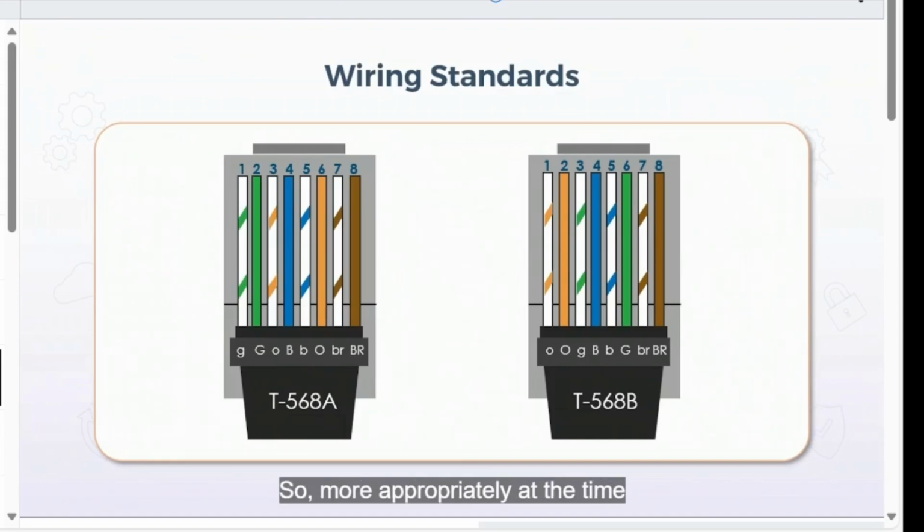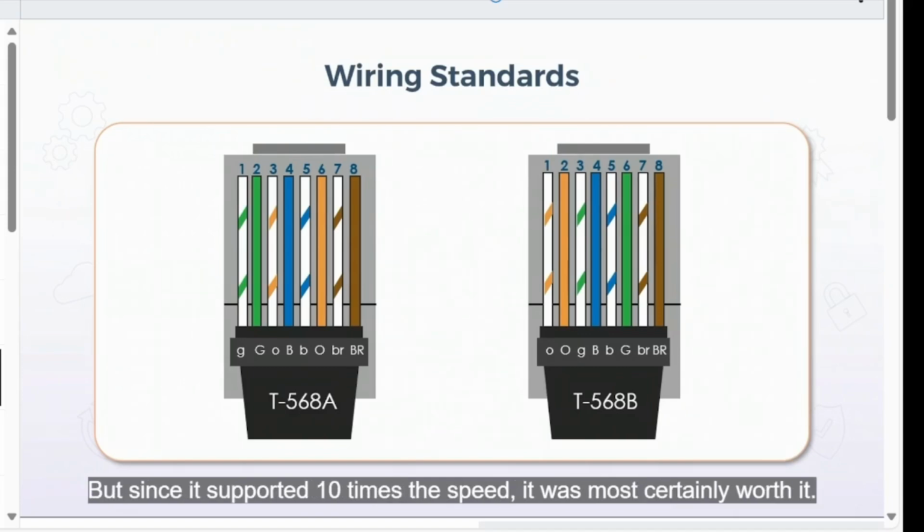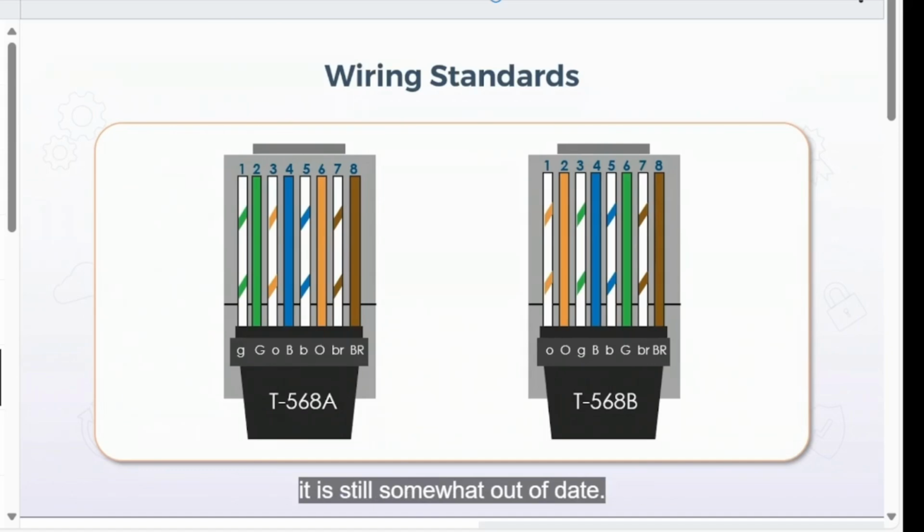But I should also mention that if you are doing your own crimping, I'd say that it won't be overly likely that the color scheme will be written directly on the connector as we see in the graphic here, because both standards use the identical RJ45 connector. So the manufacturer of the connector can't assume that the connectors they're selling will be crimped in one way or the other.